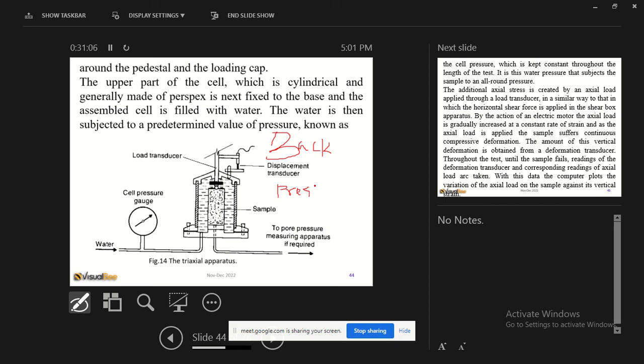Now this has some theory which we will not get into, but the idea here is, when you're applying the sigma 3, the consolidation, well, this is not the same as consolidation per se. Okay, it's the same, the idea is the same as the consolidation. So you apply sigma 3, but you apply what is called a back pressure.